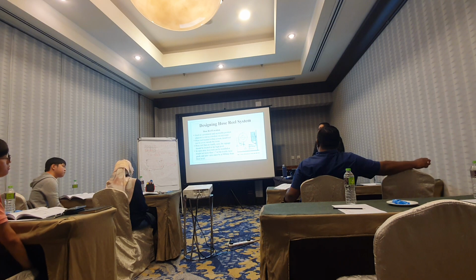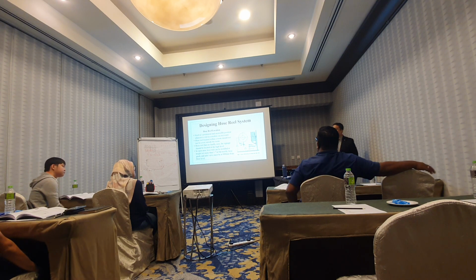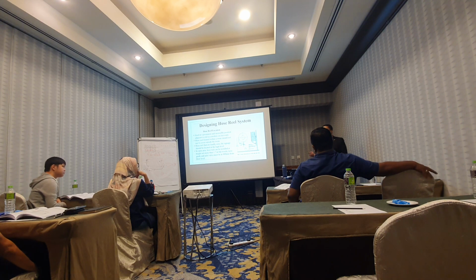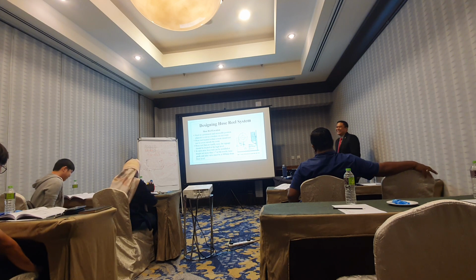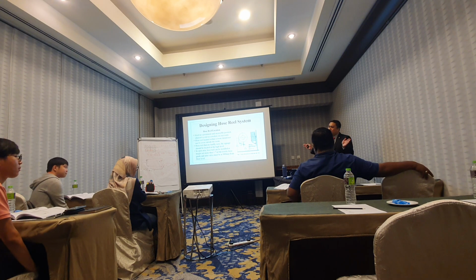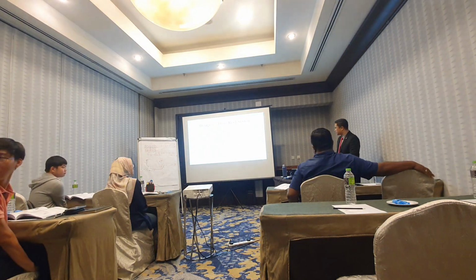But make sure the hose reel is not located inside the egress, the lobby, or the emergency escape route, like we showed yesterday. If you put the hose reel just next to the door, that makes the door width smaller. That's not acceptable. Installing a hose reel in front of an emergency door is crazy. Because yesterday you missed it, you're ashamed. The emergency door must have a clear width and cannot be reduced. Even though we are the installer for the active system, remember you must be aware of it. So crucial.